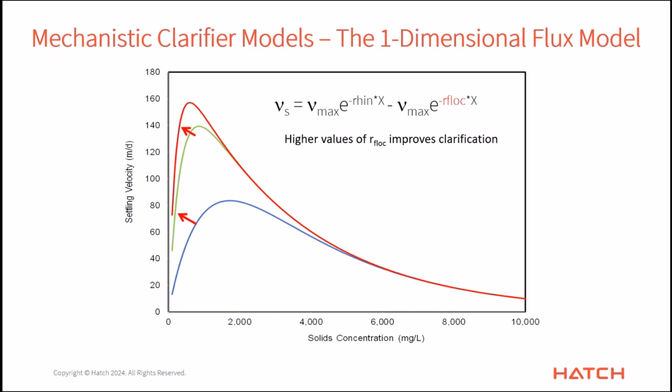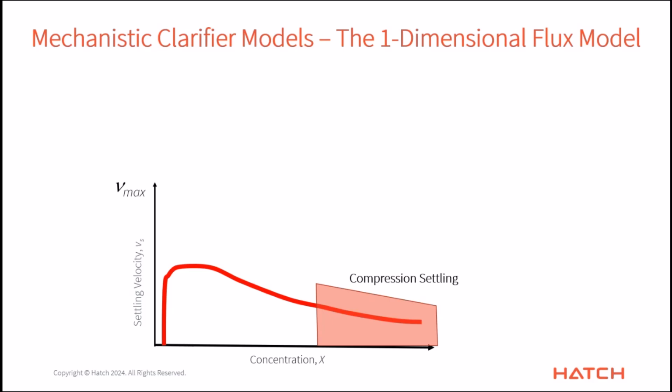And then the other parameter controls the other end. This is the low end, so this is the top of the clarifier, and the clarification parameter setting. I can affect just the aspects of the effluent solids concentration without really making much change in the lower half of the clarifier where the solids concentration is higher. Now, the problem we have is these two parameters actually act in different directions. And they're also very, very small numbers, 0.00051 or something like that, so they're not too terribly intuitive.